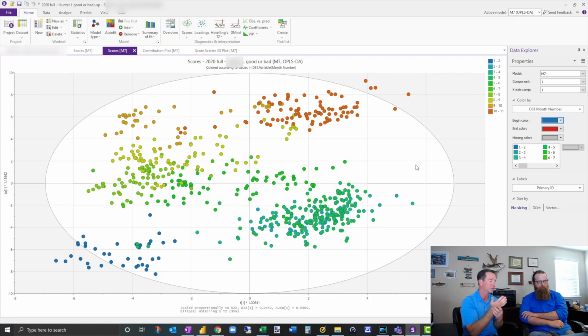And one of the things we did was, they had an airflow measurement and we made the dots bigger with airflow. And what happened was all these little blue dots way down here got huge. What they validated with us was, hey, we had a problem with that sensor and we replaced it at the end of January. Those weren't really real, right? Because we were seeing like 7,000 CFM of air, and everything else was like 3,000 to 4,000. So it was literally almost double. That's what they were seeing, right?